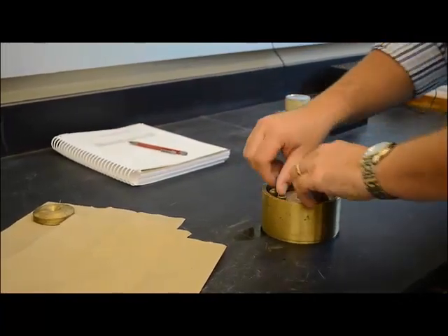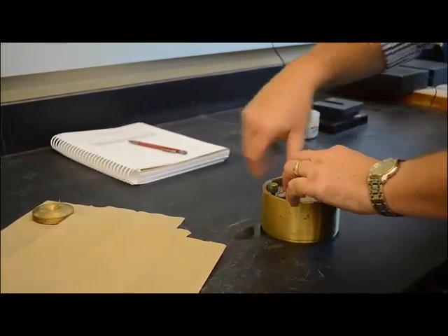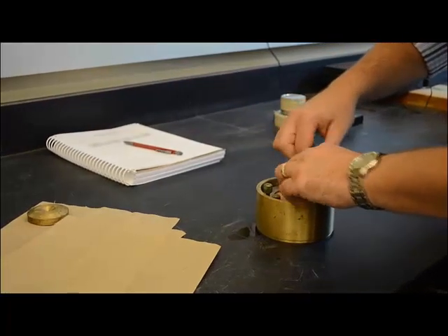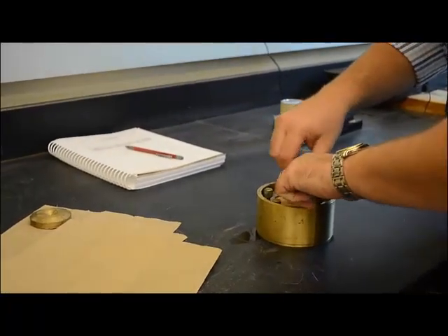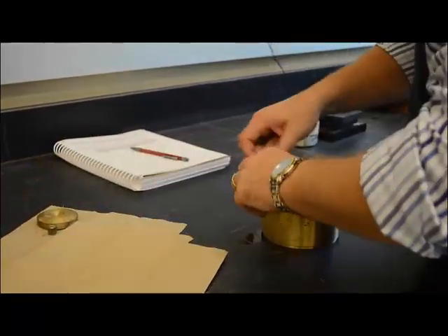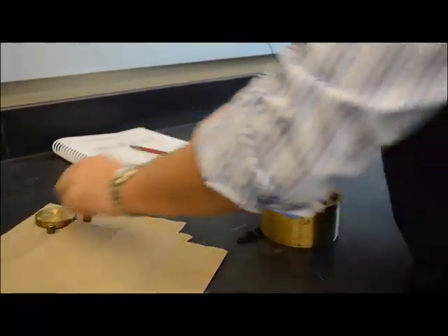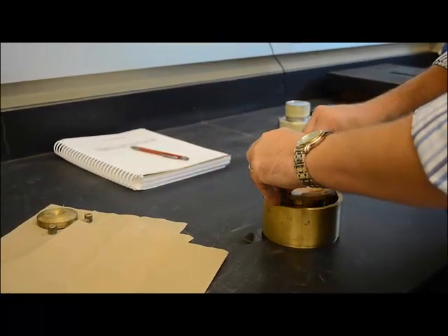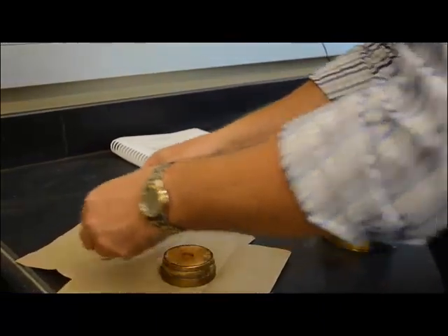And I'm just showing you the procedure to remove the soil sample from the water bath after all of the tests are completed. All of the loading increments are done. And remember, each loading increment gets a 24-hour reading. Okay, so and you want to take the time measurements accordingly. So now what I'm doing is I'm taking this apart.